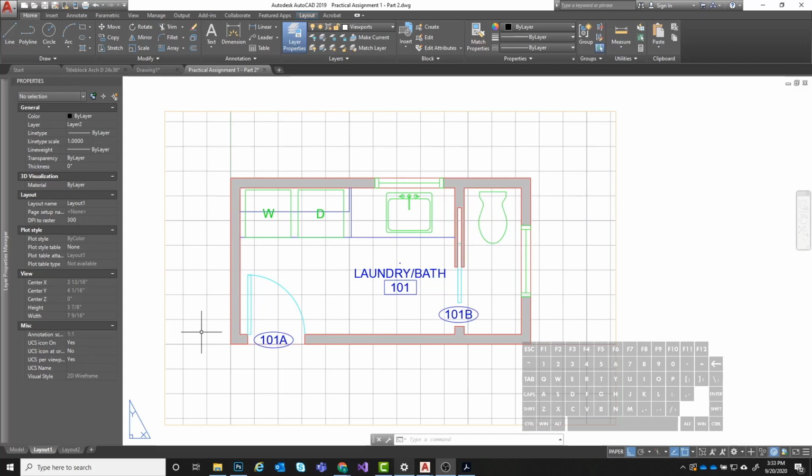And then basically, going hand in hand with those standards, they have their own plot style file. Okay, and what these plot style files do is they look at each color in the drawing, and someone has gone into this file and they've said, okay, if you see the color red, give it the thickest line weight. If you see the color blue, give it a medium line weight. And there's specific pen weights, like numerical pen weights, that are tied to each of the colors.